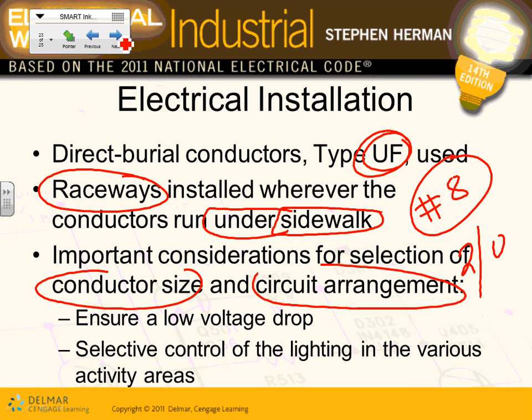Voltage drop. So don't be surprised if, when you look at the blueprints, you see a 1/0 or 2/0 for the parking lot, even though it's landing on a 30 amp circuit or a 20 amp circuit, because of voltage drop. The way they do it is they pull the feeder here, see a 1/0, and then they tap it from here going to the lighting fixture. Here's my lighting fixture, and right in here they fuse them. Here's my 20 amp fuse. You see how they control them?